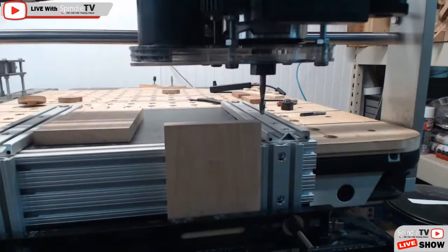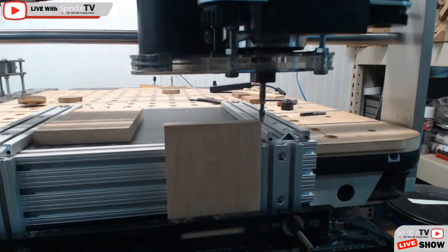All right, let's actually start carving. The first process that's going to happen is it's going to go through and do some peck drilling, and then it's going to go clear out the pockets, but it's going to go around the entire board and peck drill and all. Now I'm going to bring my Z to 0 for a moment. And I should be kissing on the top of that board, which I am. That bit should be split, which it is. So, all right, here we go.